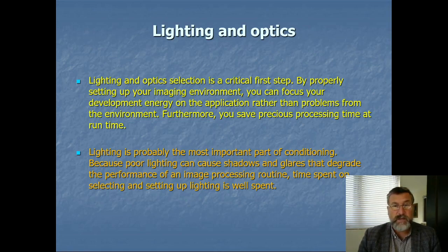So spending time on selecting and setting up lighting is time well spent. And that actually can save you a lot of work on the software side, because if you simplify things by clever and good use of lighting, then you need less image processing as a general rule, which will save you time on having to do the processing on an ongoing basis, really.